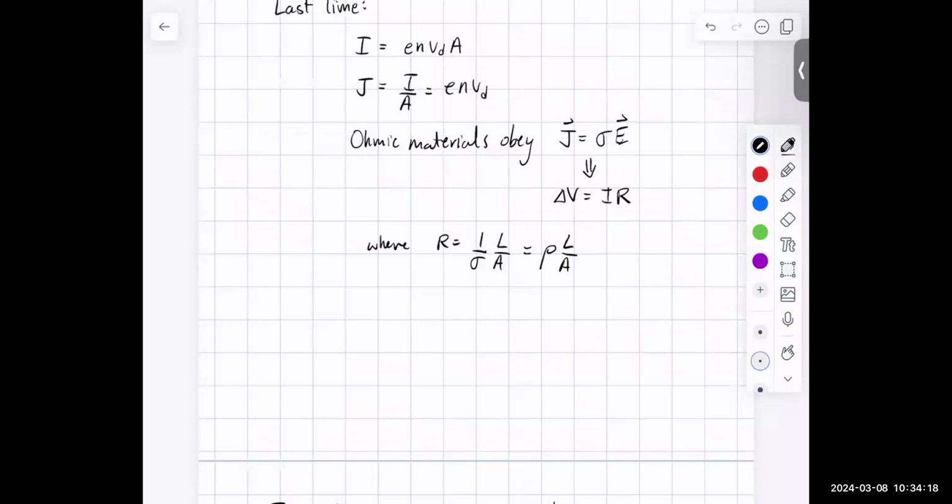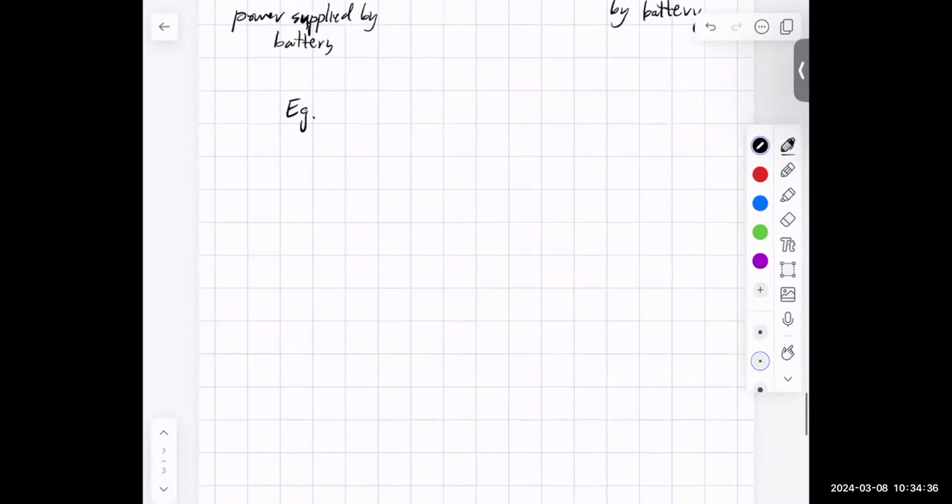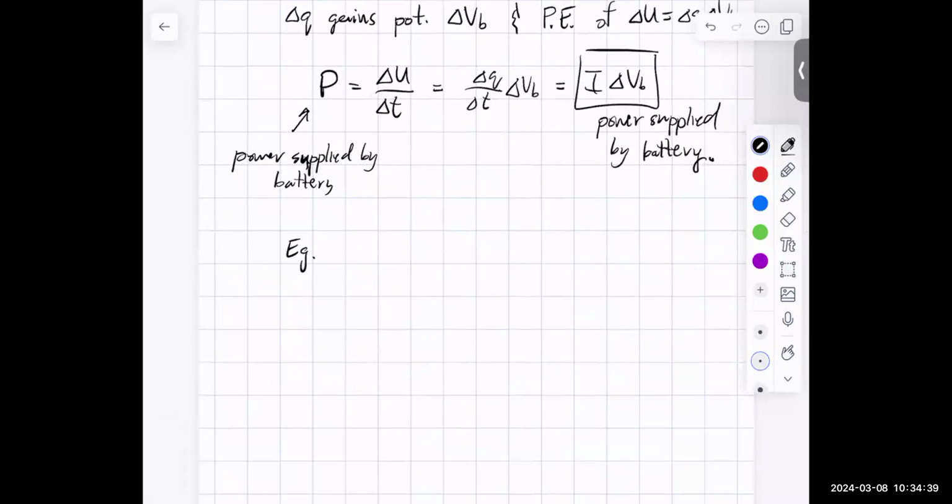It's also made of nichrome. Nichrome has a high resistivity, so that's another factor that makes the resistance large. You wouldn't make a toaster with copper wire because it would have a small resistivity and a small resistance. What we're trying to do is make our resistance large so that it dissipates a lot of power. If it dissipates a lot of power, the wire will heat up, and that heat is going to be used to toast your toast.